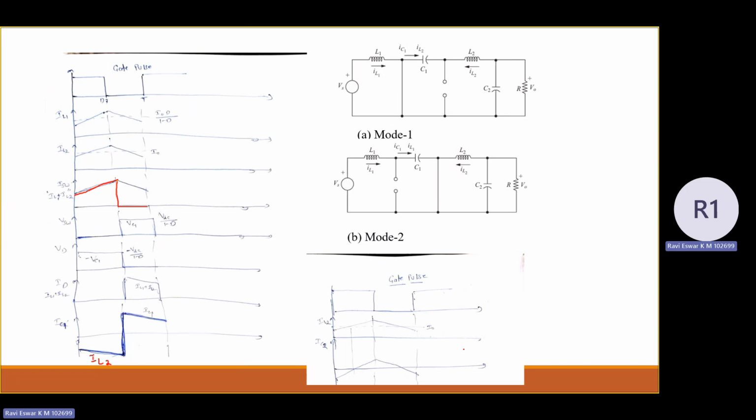So now coming to the design of elements. How many elements are there? You need to design the values of L1, L2, C1, C2. So how to design these passive components? In the previous videos, I mentioned that to design values of inductor, you need to look into the KVL equation and get del I, because the inductor design is based on the ripple current del I.